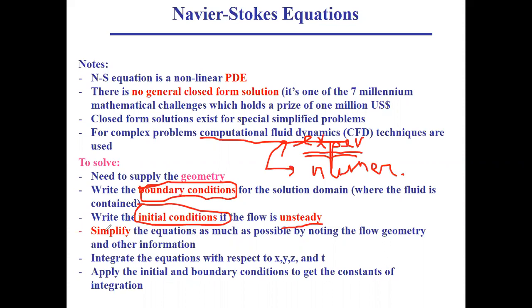Let's say for an HVAC application, you don't have electrostatic forces, you don't have magnetic forces. So the dominant forces will be the weight, the body forces, let's say buoyancy forces. Buoyancy forces will be dominant if you have a large variation in density of your fluid within space.